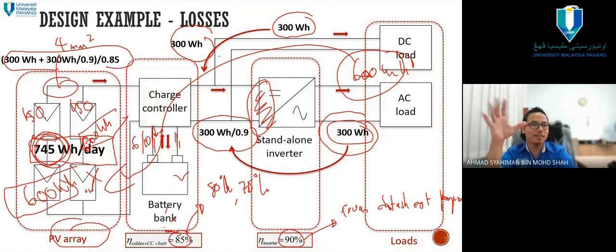If you calculate 1000 watt hour, that means you need a PV module that can supply energy with capacity of 1.25 kilowatt hours. Not 1 kilowatt hour, but actually 1.25 kilowatt hour. 25% extra, simply put. It means we need 25% extra energy so that we can get the energy for the load that we already set in our system, in our house.